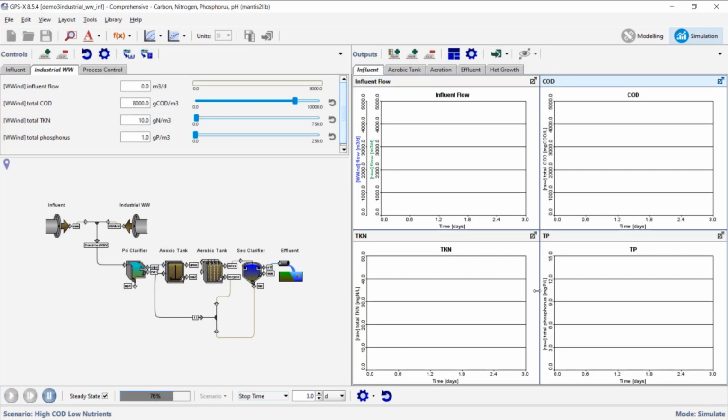So we're going to run it once here, and it's going to be a 3-day dynamic simulation. Now, if you look at this thing right here, it's showing that the wastewater influent flow coming in is equal to 0. But we're reading this in from a spreadsheet. So at about 2/3 of the way along here, this pops up. Oh, I just missed it there, but you saw it. It popped up to 250 meters cubed per day, and we're feeding that in at that rate for a period of time, and then it goes back to 0.